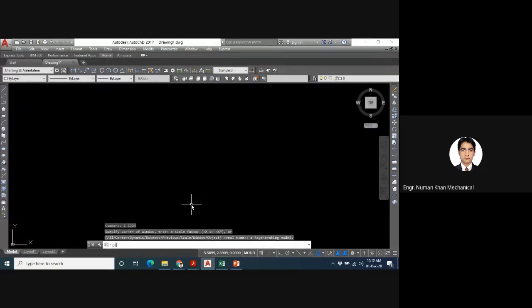Let me show you another feature of the polyline. So I'm going again to the polyline. When you select the start point, it has many options activated. You can draw an arc along with the line, you can give half width, you can give the line a length, you can give width to this one as well. What does this mean? Let's start with the arc.